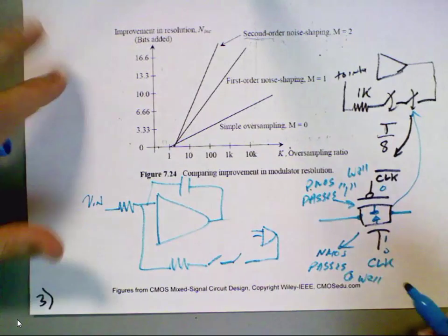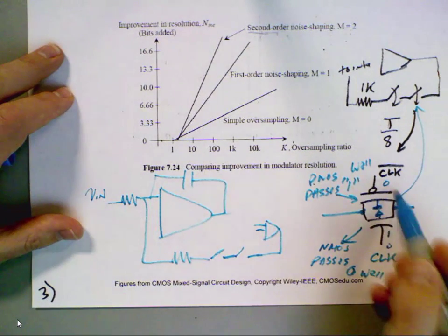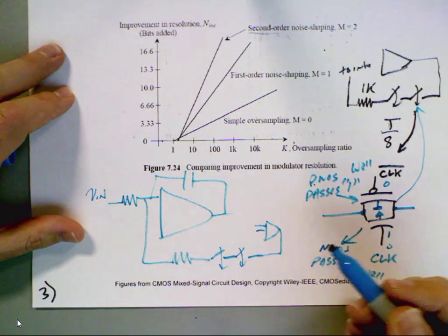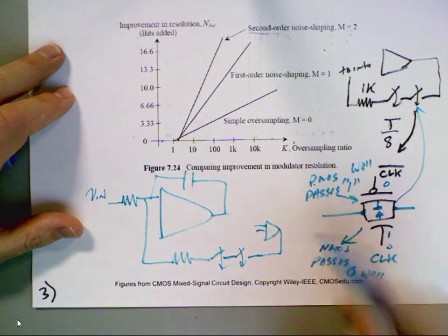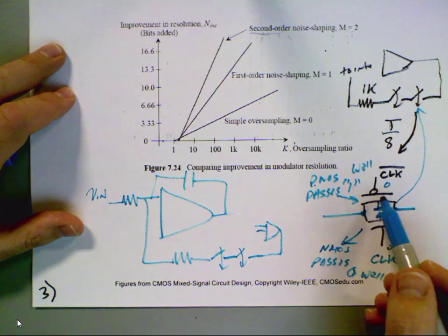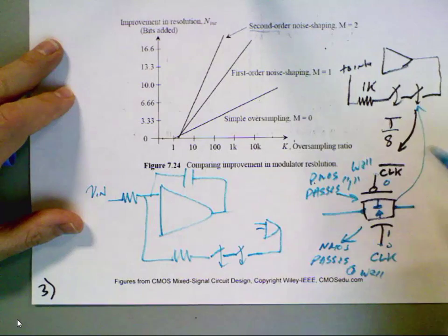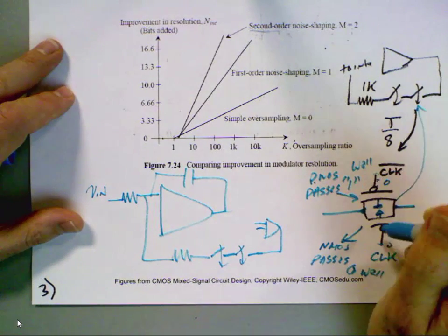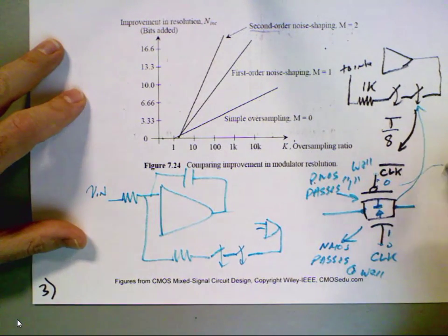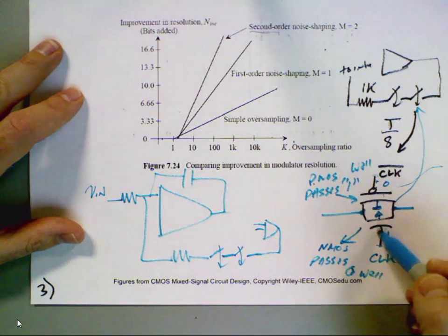This comes from the comparator. It comes down here. The concern is when you turn these TGs on, they also have a resistance. Does everybody follow that? And if you make them too wide, then they're a big capacitive load that you have to drive from your oscillator. So you've got to make sure that they're turning on and off quickly, because if they're turning on slowly, things won't work well. Okay? They have a resistance.